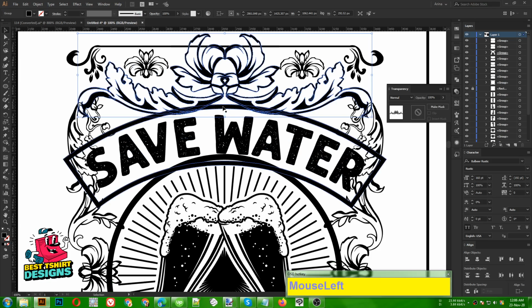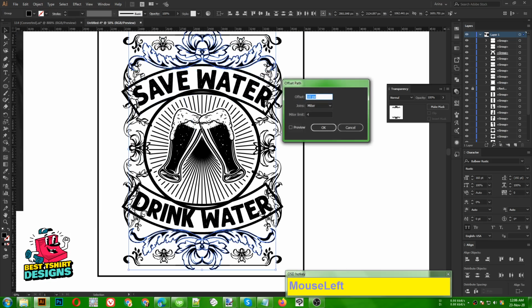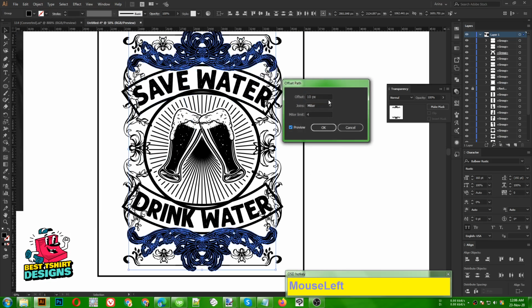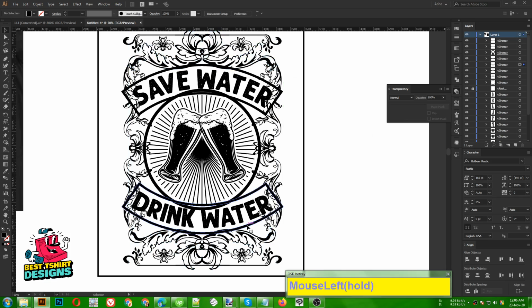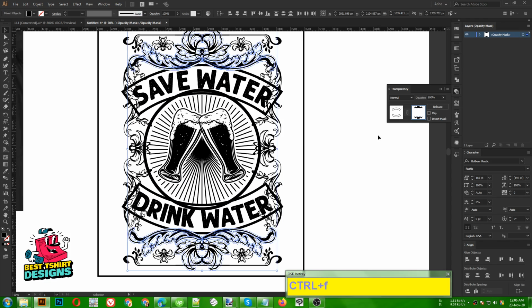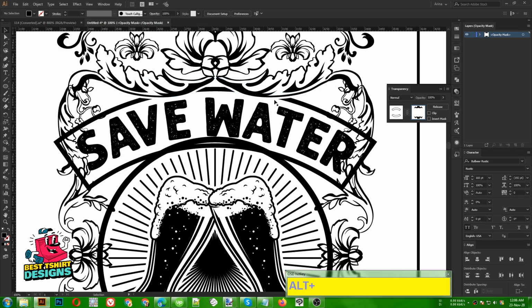This part should be on top of my rectangle, so select this one, and at the same time this one. Go to Object, Path, Offset Path, 10 pixel, maybe a bit lower, 7 pixel, that's good. Cut. Now I want that to overlap this rectangle and this rectangle, so select those to make them a group. Open their transparency, press Ctrl F to paste in front.